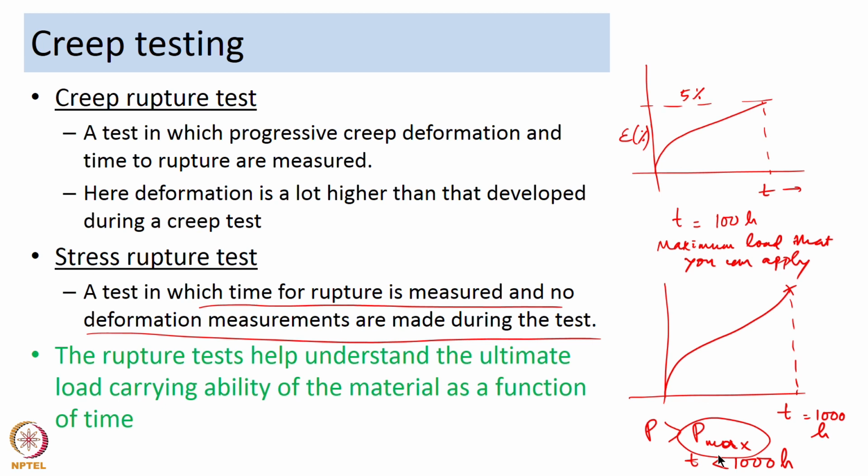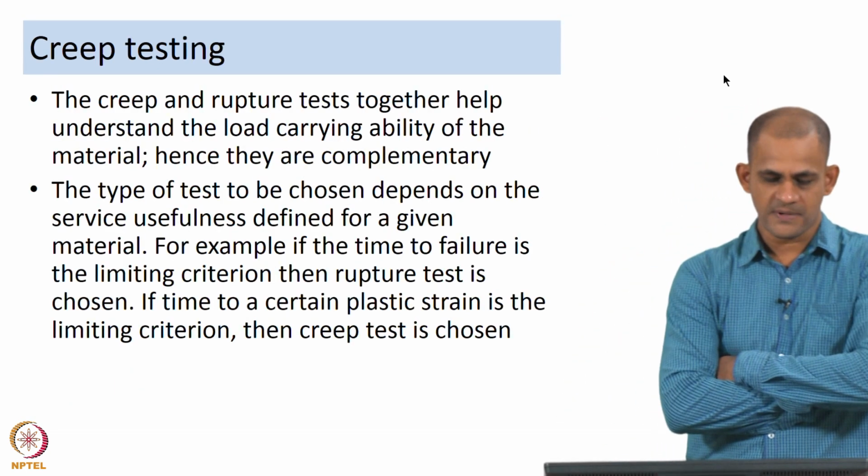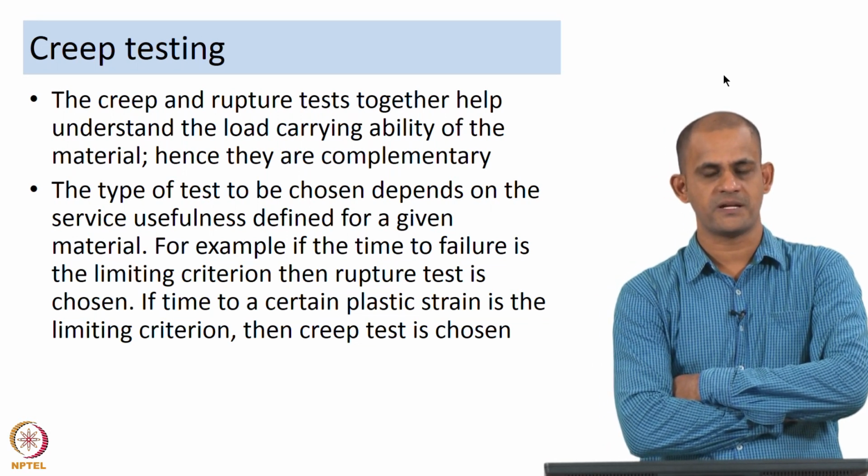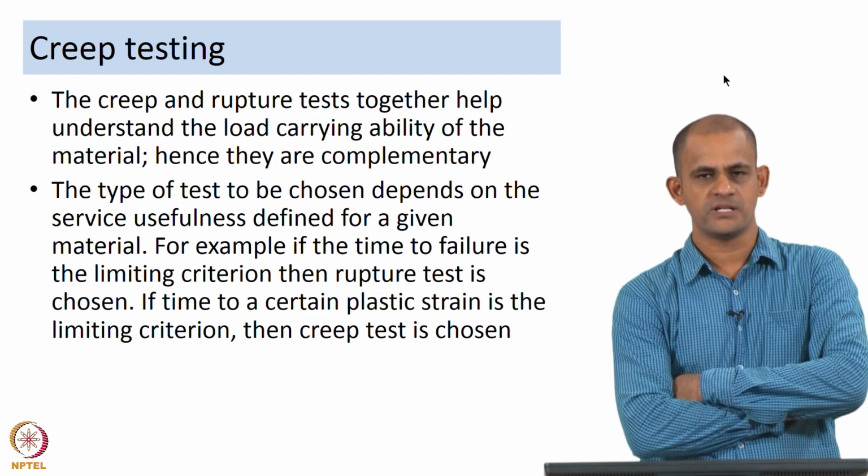So, if you look at both these plots, these together can tell you the entire behavior or the entire load carrying ability of the material. If you are defining the strain that you are allowing and the time to reach that strain, then you know what kind of loads you want the material to experience. But if you are defining the time to rupture, then you know what is the maximum load that the material can experience. So, basically the creep and the rupture tests together help understand the load carrying ability of the material, and hence they are complementary to each other.